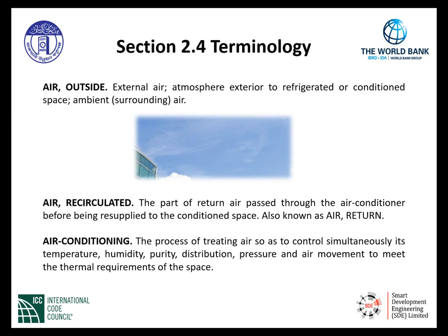That is to take outside air into our air distribution system, air conditioning system, and mix it and deliver it to what we call the breathing zone to dilute contaminants within our buildings. And we'll speak more of that in a slide or several slides coming up.